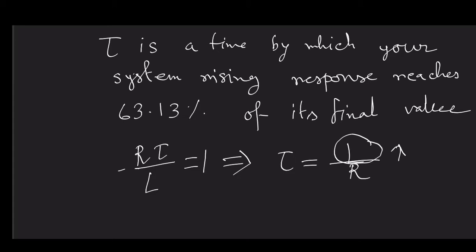While switching it off, they must have noticed that some spark takes place inside the switch. So how do we explain the occurrence of that spark inside the switch? You should think from this transient part, while you are trying to disconnect an energized RL circuit from its source.